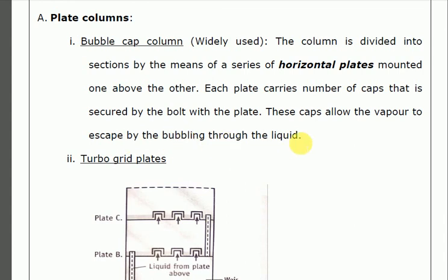The liquid will bubble, and with the help of this bubble, the cap will move a little bit up and allow the vapor to pass. The same mechanism as the whistle of your cooker. The whistle keeps the vapor secured in the pressure cooker, but when the pressure gets much higher, the pressure is released by the whistle kept on top of the cooker. Same mechanism.